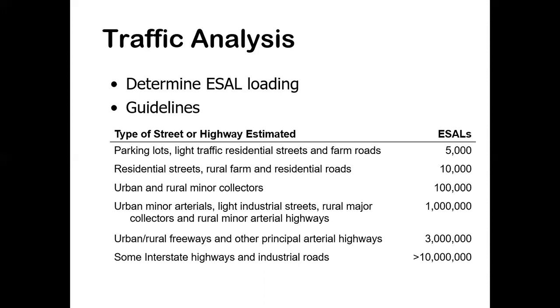But we are living in an area where traffic is always more and the loadings are not controlled. So, as an expert in this subject, I would advise you to take the actual ESALs or calculate the ESAL that is required rather than following these.